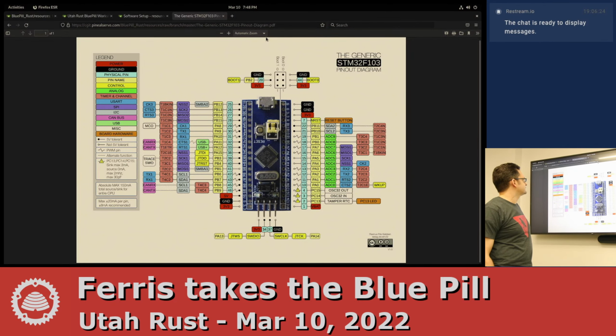Everything you connect also has to have a ground. Grounds are very important because they provide a signal reference. If you try and connect two things without also connecting their grounds, signals without grounds don't work. One of them will float higher or lower than the other. Everything will get confused. So you always got to check your grounds and keep them as tightly coupled together as possible.